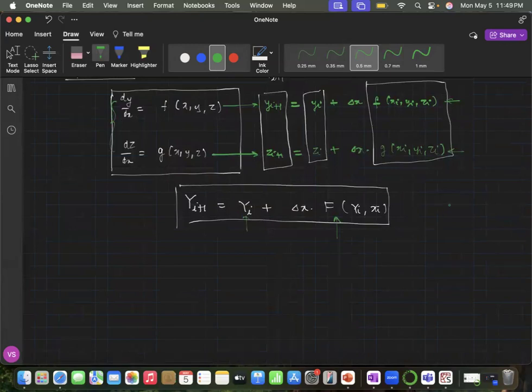So one thing that I often like to do when I have to deal with coupled ODEs is deal with a very simple example, the one that we discussed in the previous lectures. So we are going to solve, let's say, an ODE of this type, k C_A to the power n, C_B to the power m. Now over here, you see there is another variable C_B, right?